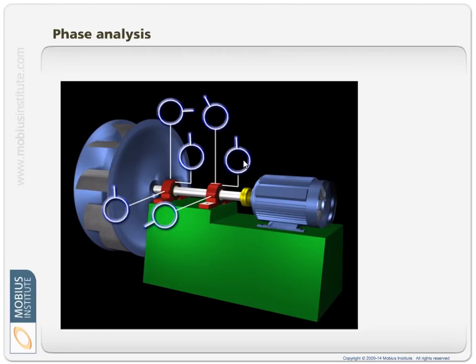So bottom line is, phase really helps us understand what's going on. The challenge with phase is how you measure it. Now, the simplest way is to have a 2-channel analyzer, carry that second accelerometer with you, because you usually just take single-channel measurements on a machine. And when you suspect a problem, you put, for example, one sensor on top, one sensor on the side, and say, what's the phase difference at the running speed between these two locations? And if it's somewhere around 90 degrees, aha! Now we take one sensor and put it in the axial direction, another sensor in the axial direction here. And we say, what's the phase difference between these two locations at the running speed? They're pretty much in phase with each other. And so that's all you've got to do.